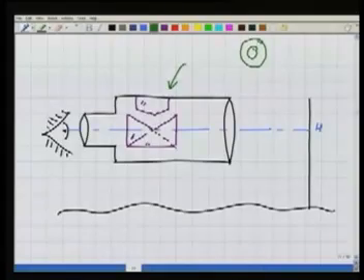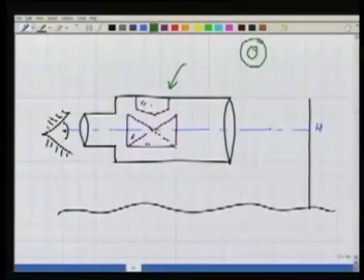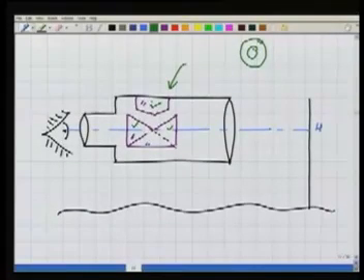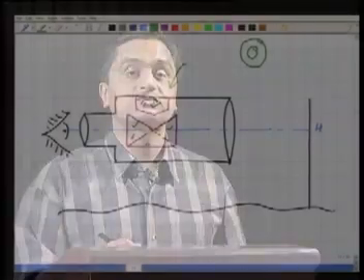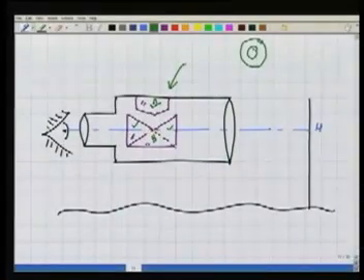But in addition, the rest of the level is the same as the dumpy level. The telescope is nearly the same. The difference is we have some extra optics here, as you can see. Now this particular part, part A, is attached to the body of the telescope, while part B is freely suspended, so this part always maintains its position. So even if I change the orientation of the level, part B will remain as it was. Now how does it help us?